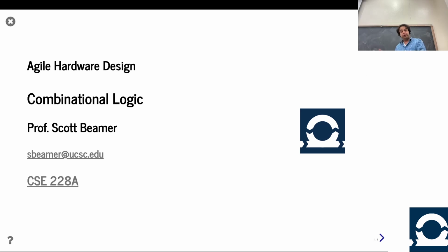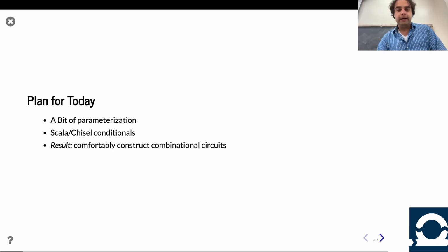Now, our generators will intermix Chisel with Scala. So, of course, the Scala, which is a program, that's not going to go into hardware. But the Chisel that's actually being done, that's all synthesizable. Whereas Verilog was designed a long time ago, so it was designed for simulation. There are certain constructs in Verilog that aren't really synthesizable. In Chisel, everything is synthesizable. And we also have the flexibility of a program wrapped around it. Let's go ahead and see how this plays out.